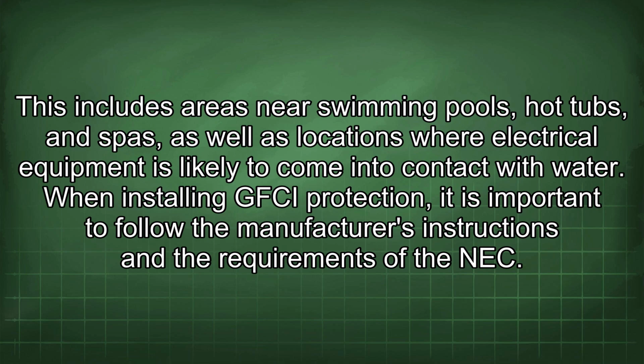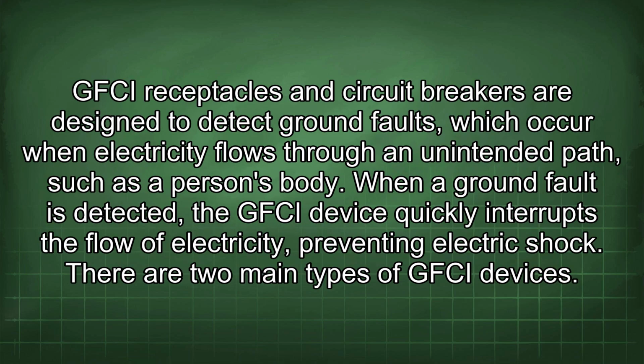When installing GFCI protection, it is important to follow the manufacturer's instructions and the requirements of the NEC. GFCI receptacles and circuit breakers are designed to detect ground faults, which occur when electricity flows through an unintended path, such as a person's body. When a ground fault is detected, the GFCI device quickly interrupts the flow of electricity, preventing electric shock.